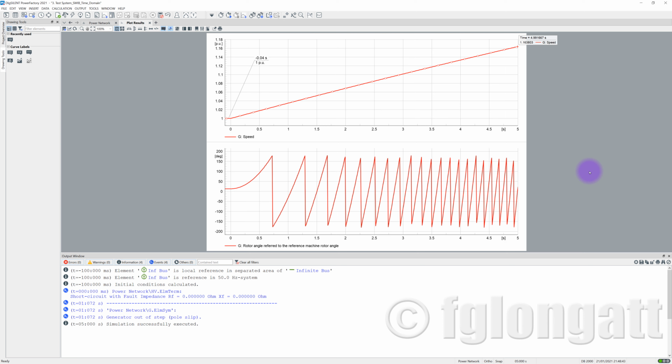Wow, this is amazing. I don't know if you realize, but what is happening in this plot? Well, this plot is amazing, because this plot is telling me that before the contingency, we have a rotor angle that we already calculated. Remember that we already calculated this angle, and it was 13.21 degrees. And that is the internal rotor angle in this machine. We are using the most simple model for this machine, the constant voltage behind the reactance, okay?